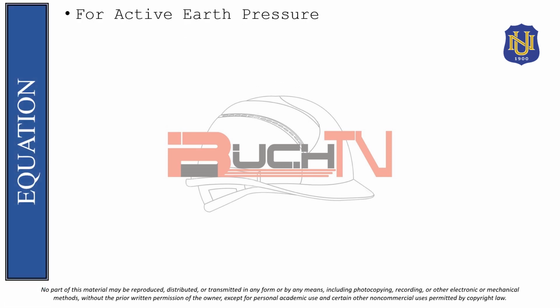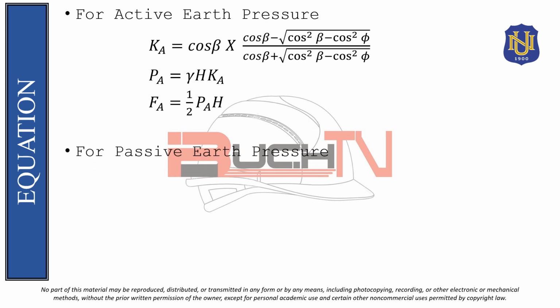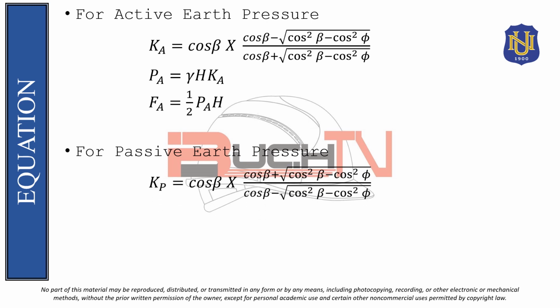So for the equations, it is still the same that we will use. The active earth pressure coefficient equation for sloping backfill, the active pressure, which is gamma H KA, and the active thrust on the wall, which is the area of the triangle, 1/2 P sub A times H. Then, for the passive earth pressure, we will have K sub P is equal to cosine of beta times cosine of beta plus square root of cosine squared beta minus cosine squared of phi, divided by cosine of beta minus square root of cosine squared of beta minus cosine squared of phi.